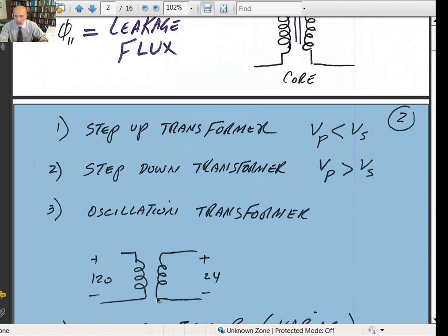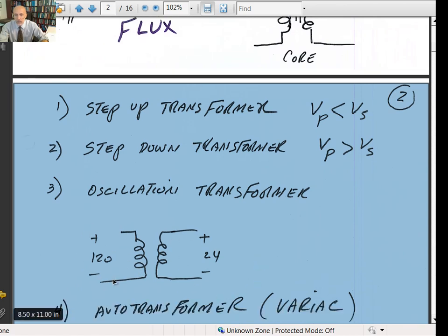What it really does here, not only does it step down the voltage, it also provides isolation from AC to go to the DC. So the AC is grounded, but you want to isolate the ground for DC, and you can do that with what's called an isolation transformer, because the transformers are magnetically coupled but electrically isolated. There's no electrical connections. Unless it's an auto transformer, that's different.